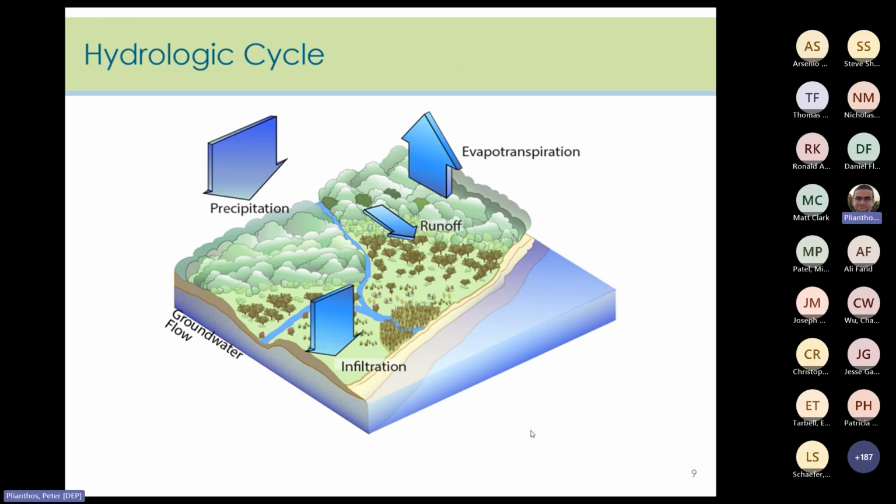Putting what we have covered together, we can then discuss the hydrologic cycle. For an undeveloped site, a large portion of the precipitation, represented by the largest arrow on the graphic, supports vegetation, resulting in evapotranspiration or infiltration, which maintains groundwater flow. Typically, there is little runoff and it flows over land to a water body.